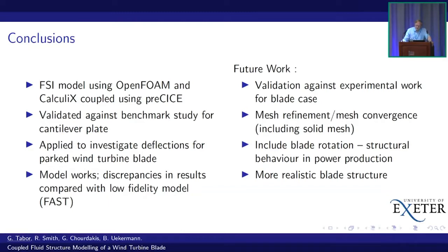I hadn't thought of it from the Calculix side. From the OpenFOAM side, I'm regarding it as a fairly straightforward alteration. Use SRFFoam, basically, in a cylindrical domain. I've got to think about the physics here, but I would presume we could include any necessary Coriolis terms and centrifugal terms into Calculix as explicit forces if necessary. But yeah, that's a good point. I hadn't thought about that.